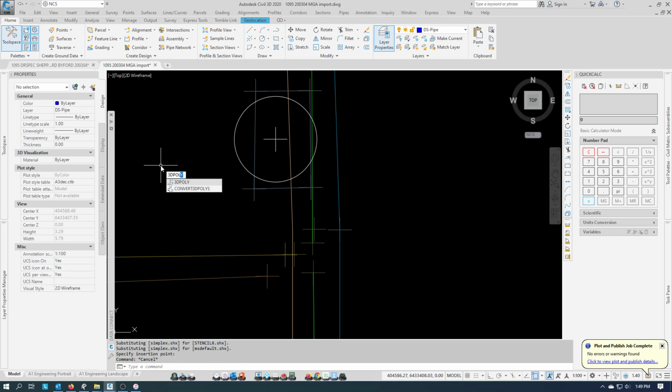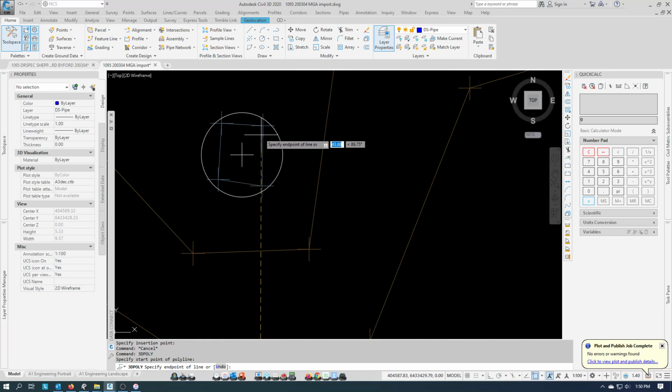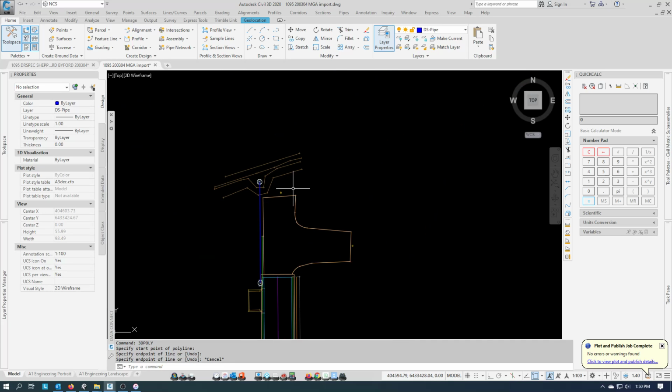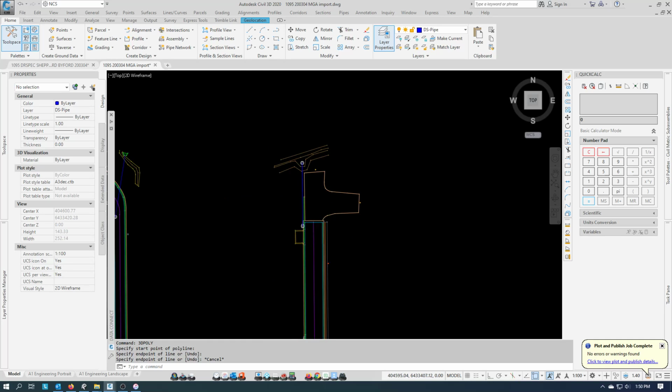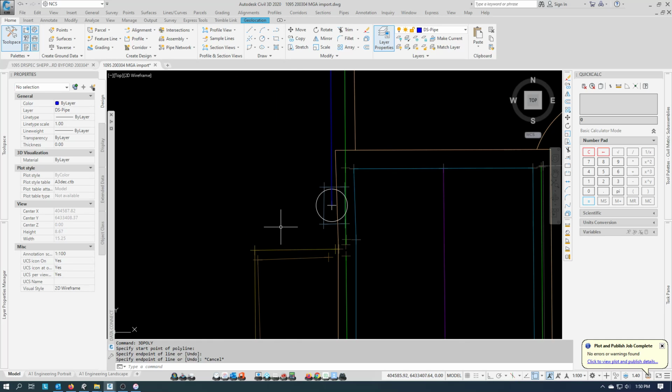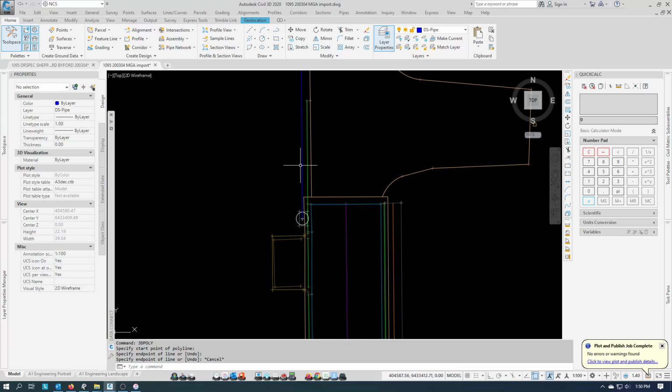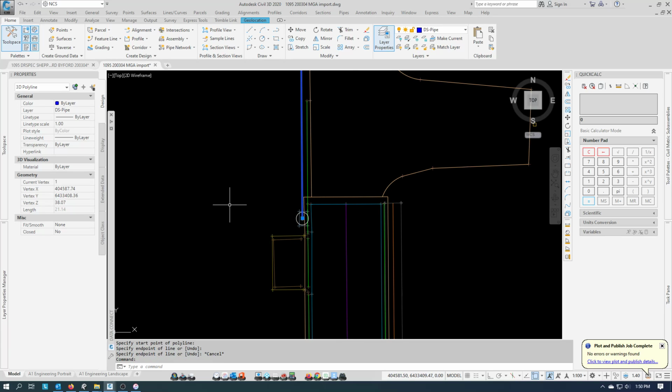So as a consequence, we use a 3D polyline to draw the pipe so that we can assign height at each end. When we export the GIS data, we can actually export to Z values rather than having to key them in. It does make it just that little bit easier to